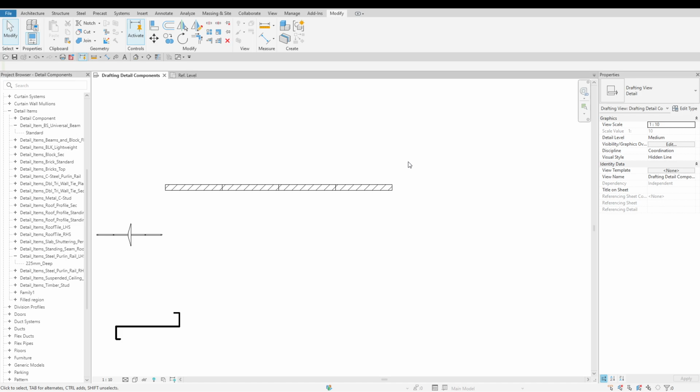Let's say the plywood was drawn at 20 mm thickness in the 2D detail component. When you place the component along a section line, it will render the plywood at that exact thickness, stretching only in length based on your input. If you need to adjust the thickness, you'll first need to edit the 2D detail component family and modify its geometry or parameters accordingly. As always, your exact workflow may vary depending on the specific design intent and project requirements.